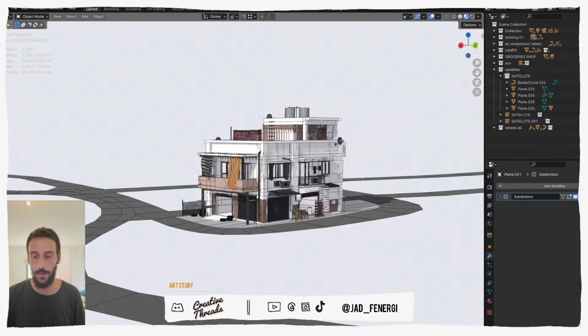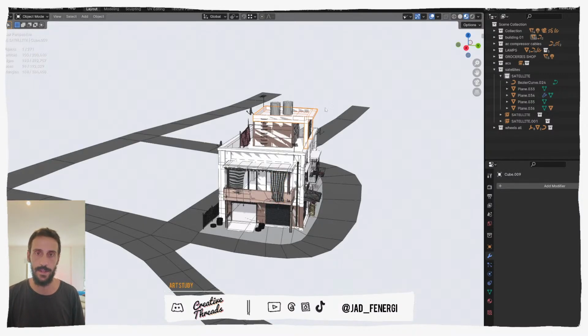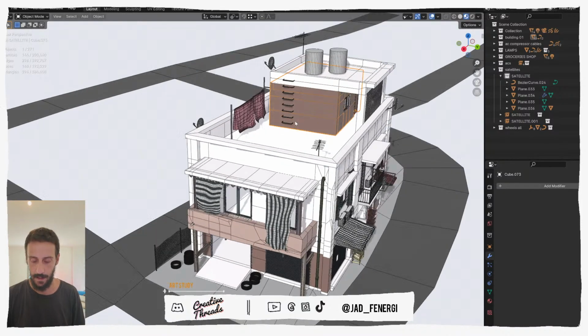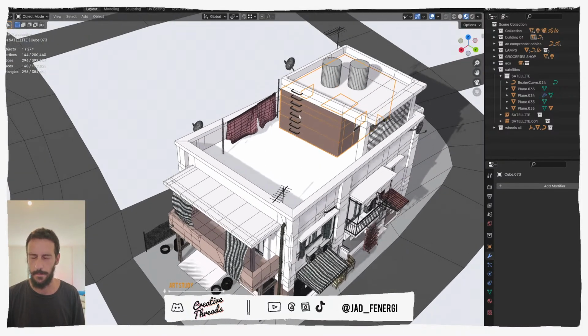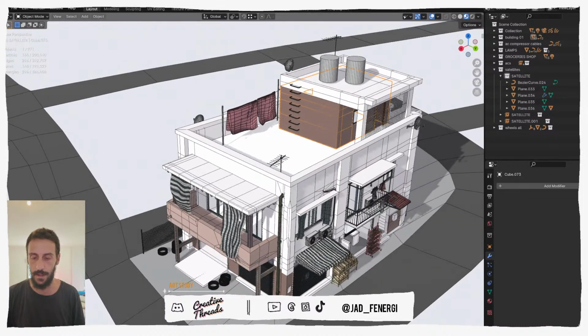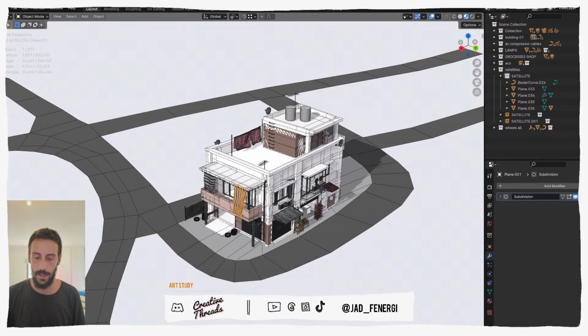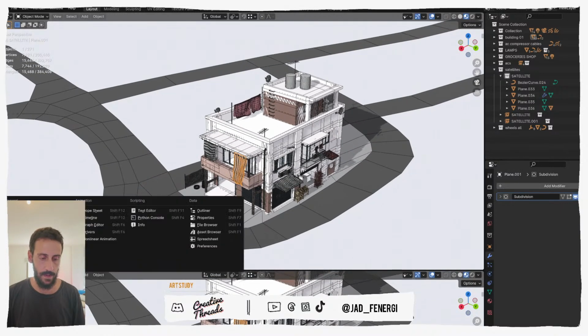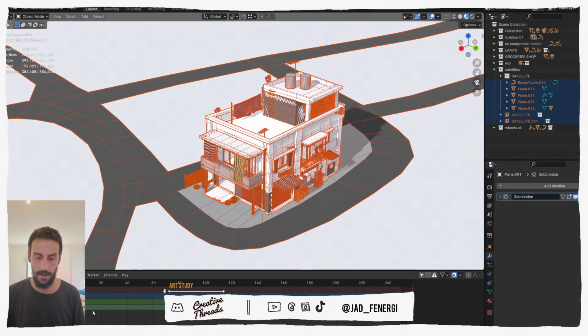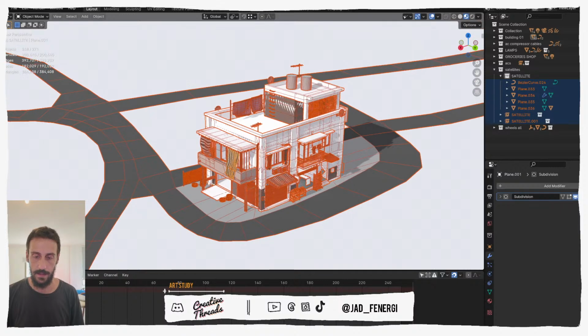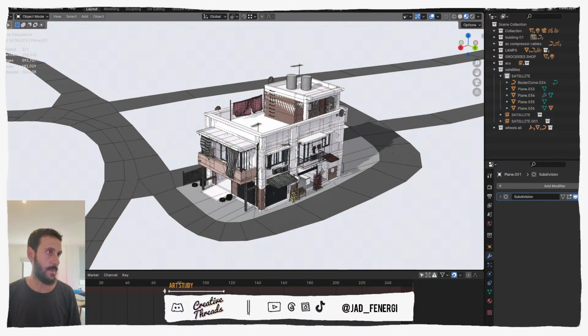We were fine rotating around the building and stuff like this, it was just edit mode that was suffering. Eventually, I just opened the dope sheet, picked everything, and deleted whatever keyframes I had, and suddenly everything went back to normal.